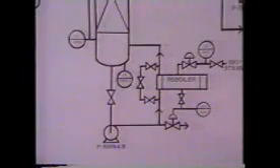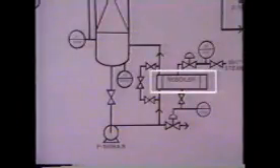For the last few minutes, we've been looking at some of the ways that feed rates affect column equilibrium. Now let's see how the operation of the reboiler can affect this equilibrium. When the column is in full operation, the reboiler provides the majority of the heat used to vaporize the mixture. The reboiler not only supplies heat to the column, it also vaporizes any overhead product that may have come down the column. This means that the reboiler plays an important role in maintaining column equilibrium.